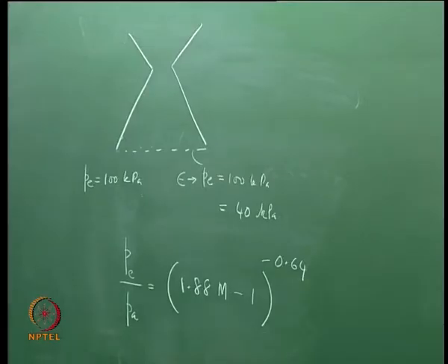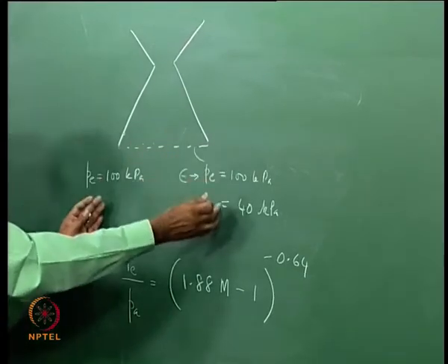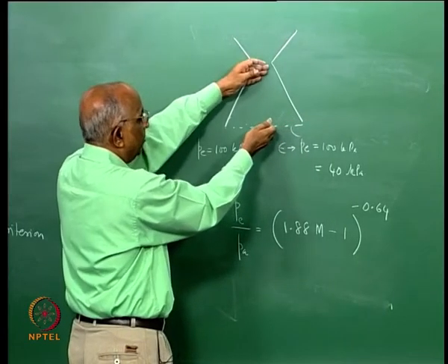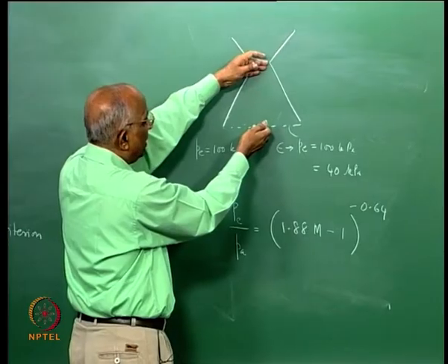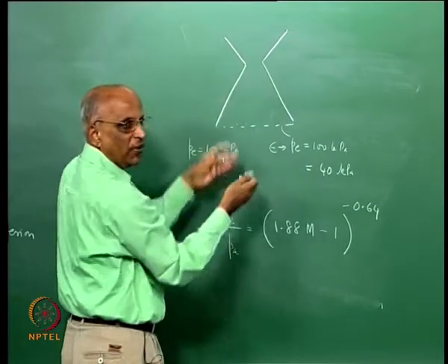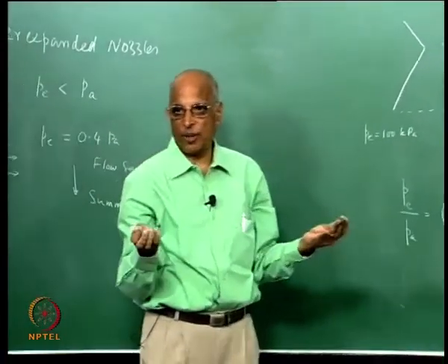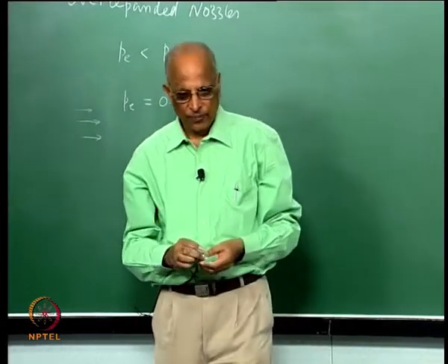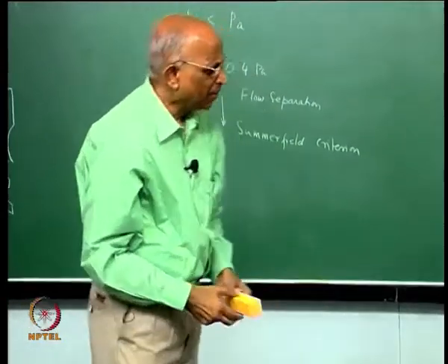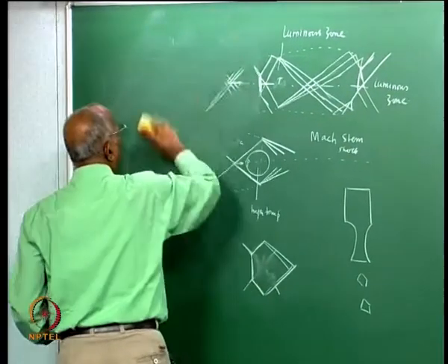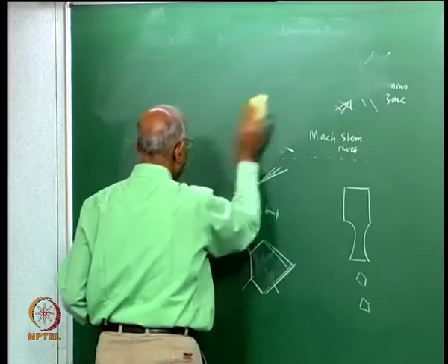Therefore, I hope by now we get a feel for a nozzle. We find that the nozzle area ratio depends on the ambient pressure. Ambient pressure keeps varying in the flight, and therefore we need variable area ratio nozzles. The moment we talk of variable area ratio nozzles, it is also necessary for us to consider the problem of underexpansion and overexpansion. By underexpansion we lose performance, by overexpansion we get side loads which are harmful. Having seen that, let us go to the next phase, wherein we would like to know a little bit more about the thrust, or the force generated by the rocket.